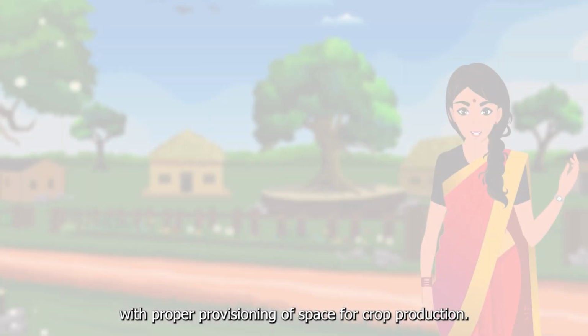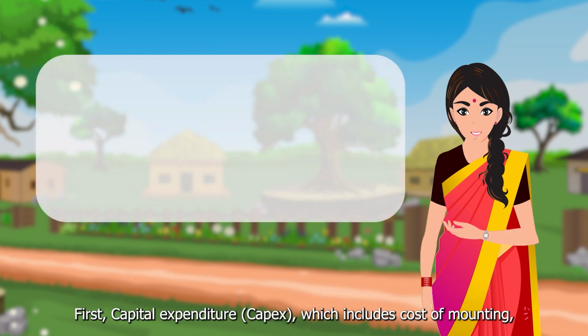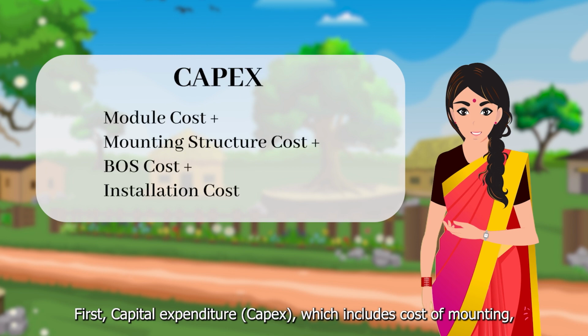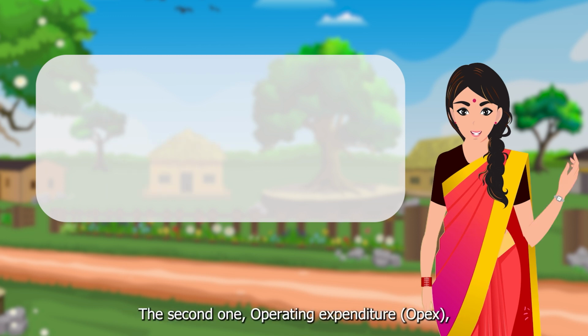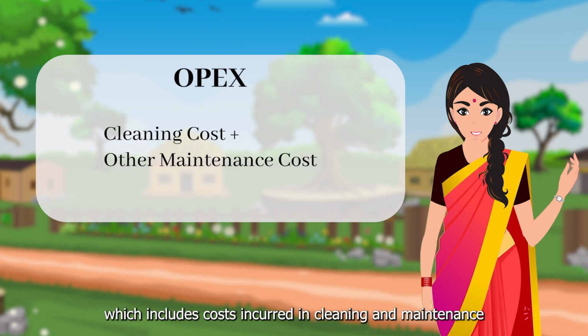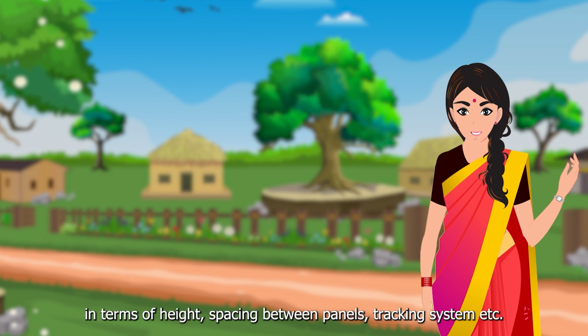An agrivoltaic system of 150 kilowatt power can be installed on 1 acre of land with proper provisioning of space for crop production. There are mainly two types of costs incurred in the installation and maintenance of an agrivoltaic system. First, capital expenditure, that is CAPEX, which includes cost of mounting, balance of system, module, and installation cost. The second one, operating expenditure, that is OPEX, which includes costs incurred in cleaning and maintenance. The cost of mounting structure and installation varies as per the specifications of mounting structure in terms of height, spacing between panels, tracking system, etc.